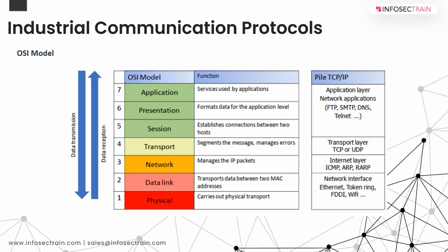Prior to all these intelligent communication protocols, RS-232 or RS-485 or a radio link was the common transmission mode, right? And it can also be carried out by an electrical signal till a PLC or a DCS without using any computer protocol. But there are certain challenges, the complexities of maintaining. If it is for just five IOs, it is okay. But if there are 1,000 or 10,000 IOs, that doesn't make sense. The maintenance is a headache, the troubleshooting is a headache, the complexities increase, and it doesn't warrant the cost, right?